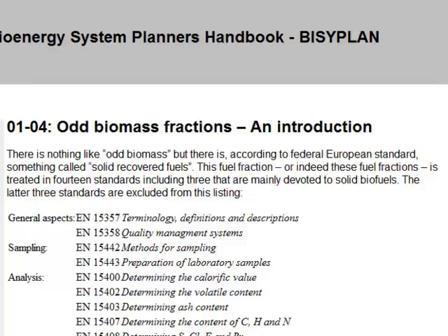That is why source separation of waste is such an important part in a bioenergy-based system or a biomass-based energy system. You cannot mix lignin-rich material with biodegradable material and hope to get an efficient and well-working anaerobic digestion process with a high efficiency, because the lignin will basically not be digested.